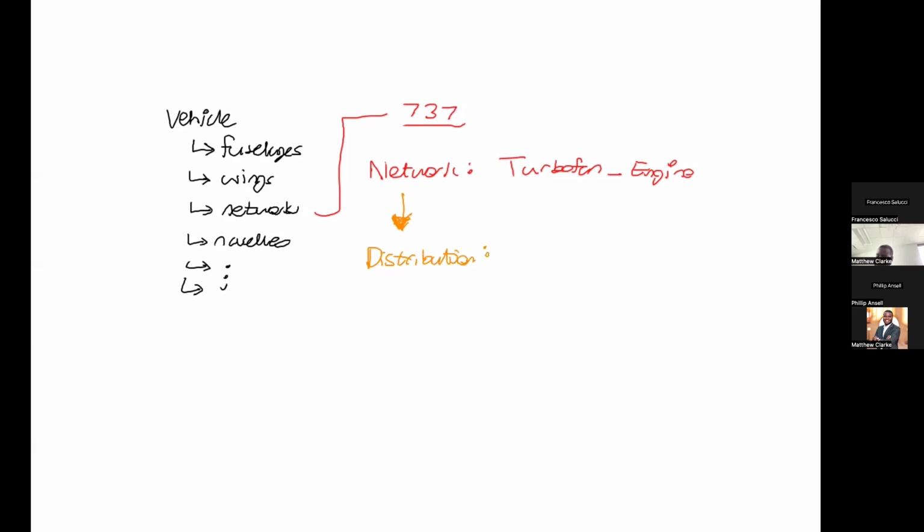And for a turbofan, we have fuel lines. So we model everything in the turbofan network inside of classes called fuel lines. And the reason we do that is because hypothetically, if you want to have multiple independent fuel lines, you can, right, on this network. Does this make sense to everyone? But for our case, we only have one of these, right? We only have one fuel line, but you really can model multiple because fuel lines is a class, right?